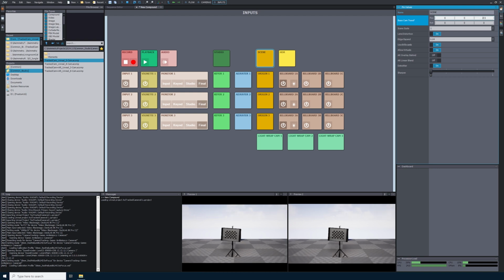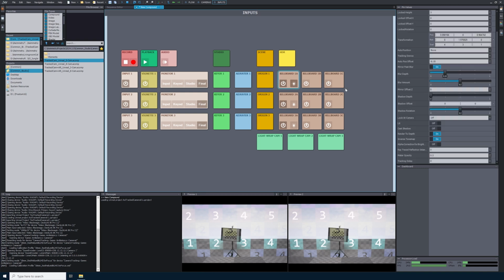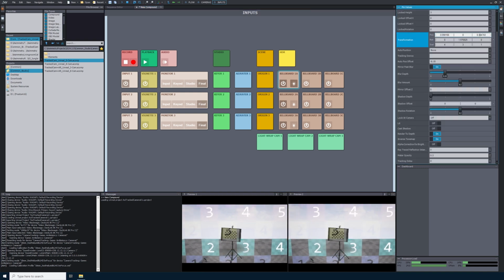As I adjust the base cam transform of my scene to move further away from my billboard, you can see that my billboard is being cropped through the floor. This is because the billboard isn't moving with the scene. When we move the scene, we will need to adjust the position of the billboard. As I mentioned before, the distances are 1-to-1 between the virtual and physical world. So if I move my scene, I will also need to move my billboard. If you've moved your scene and now your billboard looks odd, this is how you would fix that. Just remember that when you move your scene, you need to update the placement of your billboard.